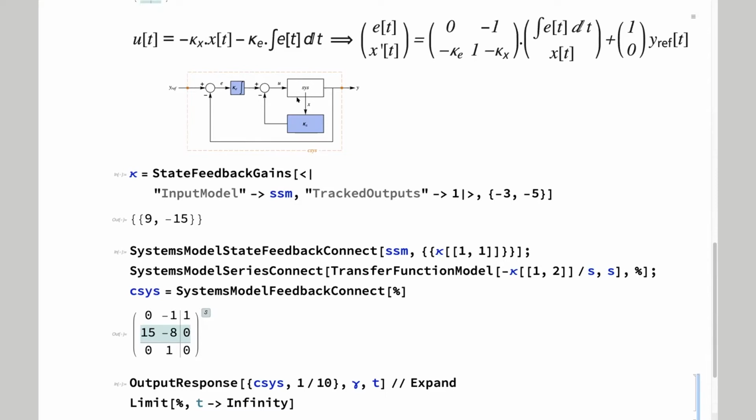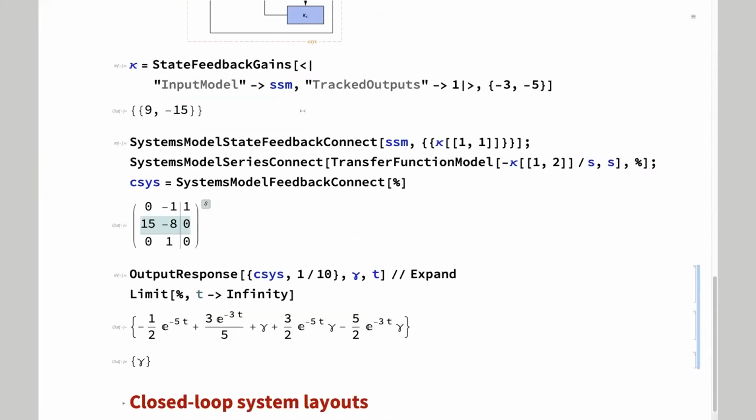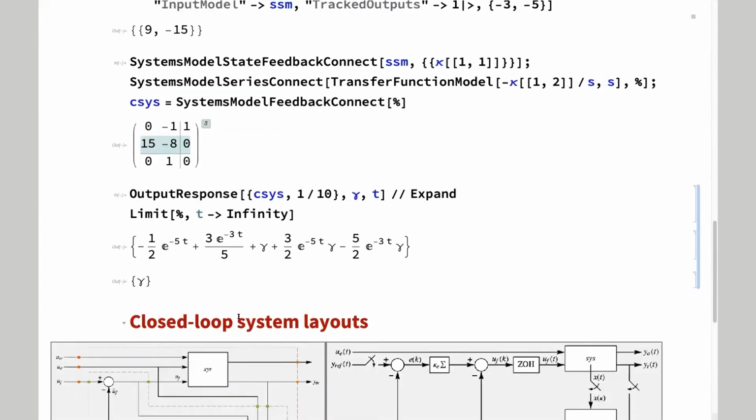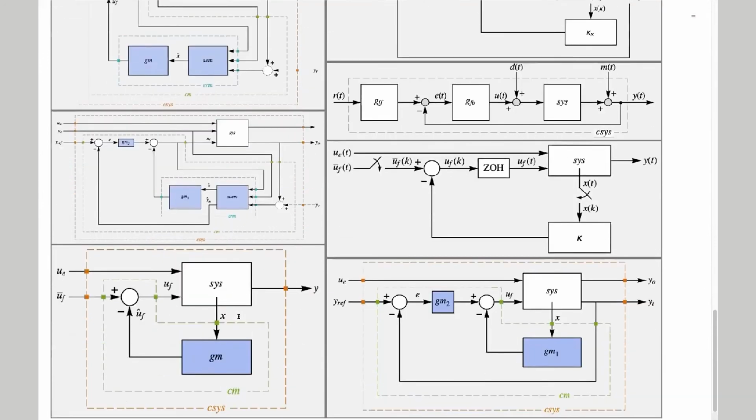Sometimes we could have a continuous time system that needs to be put together with a discrete time controller, which is a sampled data configuration. And so we could have all these different kinds of layouts. Once we have these different kinds of layouts, then getting the closed loop system, computing what's the controller model, computing various other aspects of the system, it's not difficult, but it's not trivial either. And that is the motivation for this effort, so that all these routine computations that are part of this design are automated and readily available as properties.